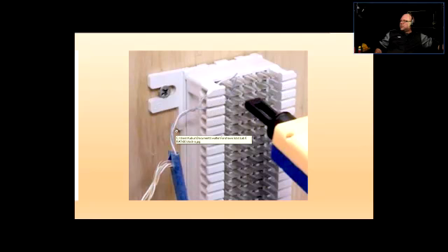So if you want to connect two cables with 4 pairs, let's say you just want to connect this one pair, you punch it into those 2 slots. The top one right here would be the white blue, for example, and the bottom would be the solid blue. So the white blue would be carried on. If you want to butt into it, you would just put another cable into this one or that one or that one. Okay, so this will be the same connection for another wire from the other side, and the other connector for the conductor for the same pair, you would use the bottom row. All right.